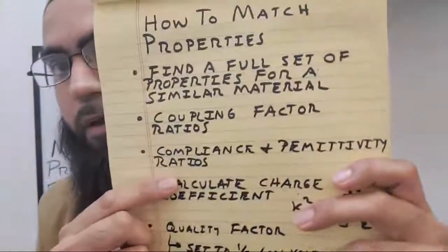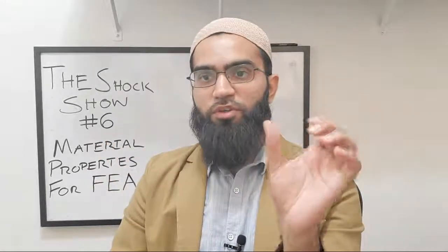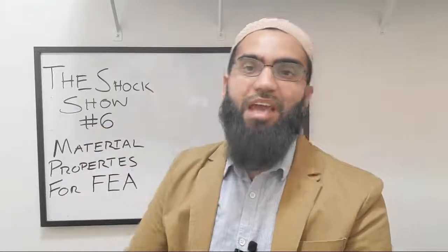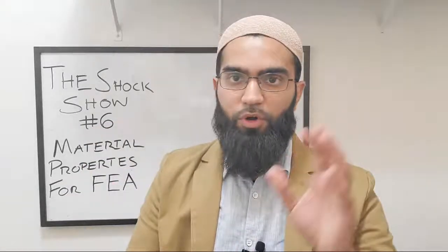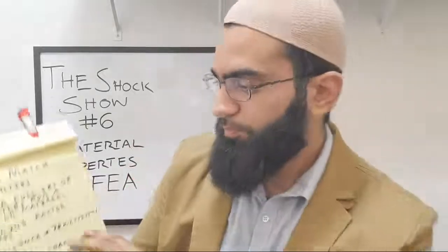And you do the same thing for compliance and permittivity, that you provide those ratios. You get the ratio of the 3-3 direction of the permittivity, and you apply that ratio in reverse. Now after you find the initial one, let's say your new material is 2200 and the material that you want to simulate has a permittivity of 1900, you get that ratio. Then you can also use that ratio to back calculate what the permittivity in the 1-1 direction is going to be as a result for your original material with only a partial data sheet.